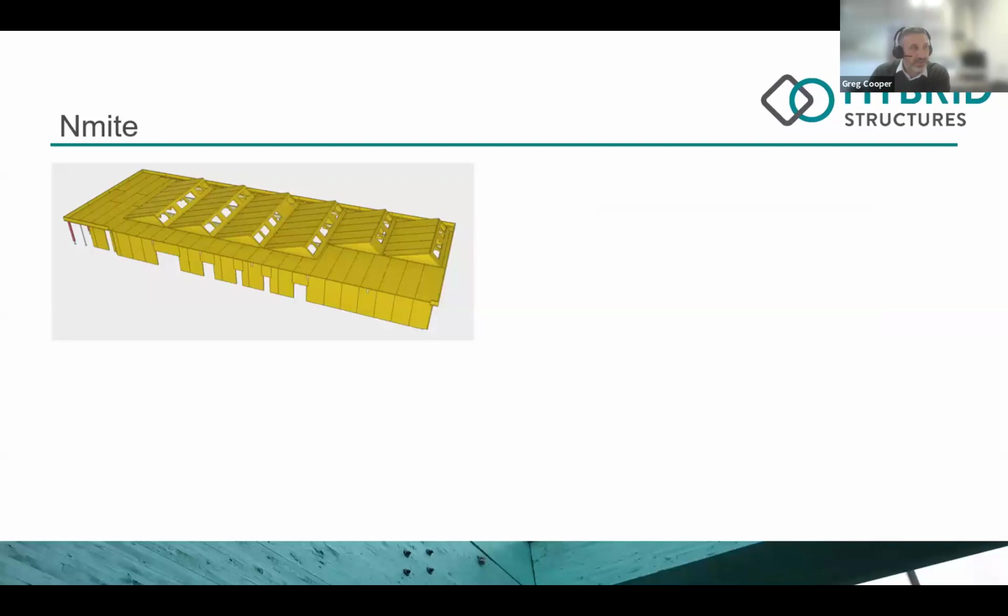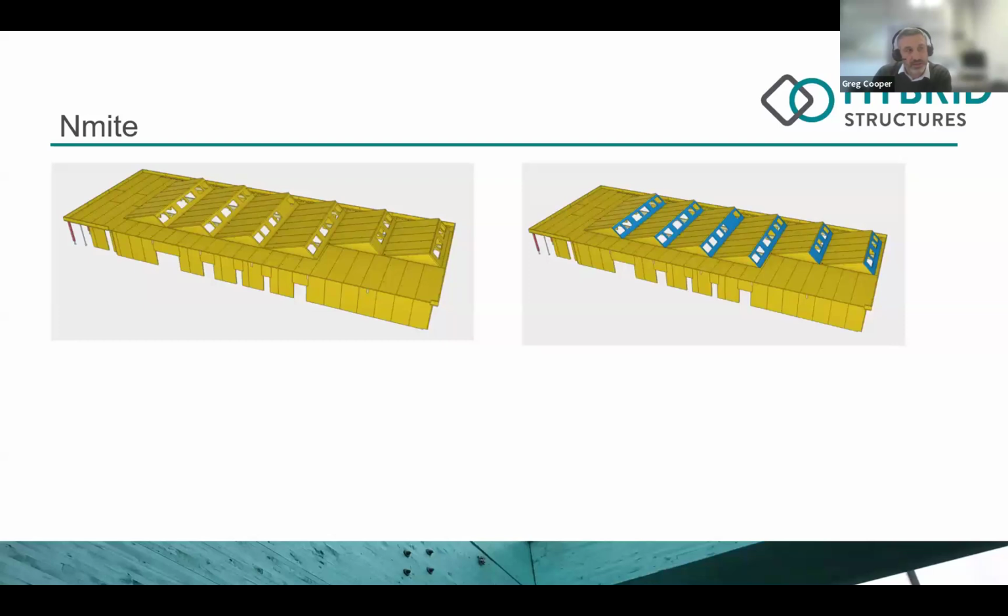So as can be seen there, that is ultimately what we delivered. That's the cross-laminated timber acting as the roof, and as the walls around the perimeter. It looks very simple, and these are things we do day in, day out. One of the key things we did here was work closely with the architect to make sure these blue elements were sized to the maximum size a panel could be to get it to the UK and onto the site. That enables those blue elements to come to site as a single panel and be lifted in as a single element.